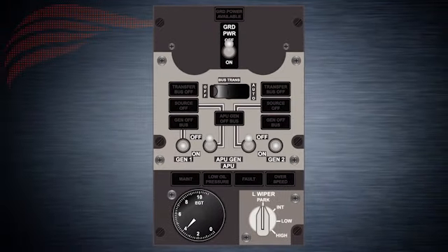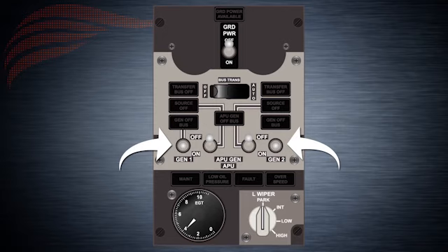Last but not least is the bus switching panel. This panel has the following switches. A gen switch that is spring-loaded to neutral and has the following positions. On. Connects the IDG to the related AC transfer bus and disconnects any previous power source, like for example, ground power. Off. Disconnects the IDG from the related AC transfer bus. When the related AC transfer bus is not being powered, a gen off bus blue light illuminates.